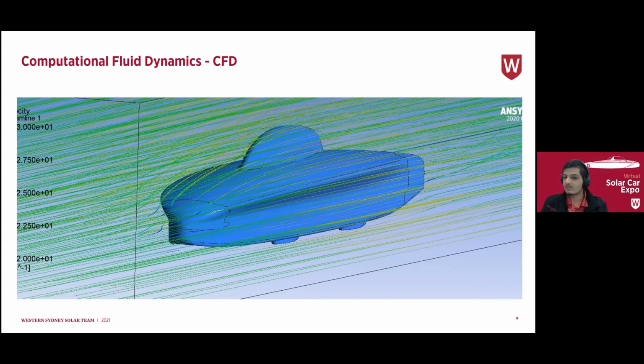Compared to FEA simulation, CFD has many more cells in its mesh, and the mathematical model it needs to solve is also much more complex, leading to many more simulation parameters that you can tune and also much higher simulation times. Fluid mechanics involves nonlinear processes dealing with inherently unstable phenomena such as turbulence, meaning the solutions are not always constant, which means that the calculation iterates until the results start converging onto one. This makes CFD simulations very hard to get right and accurate.